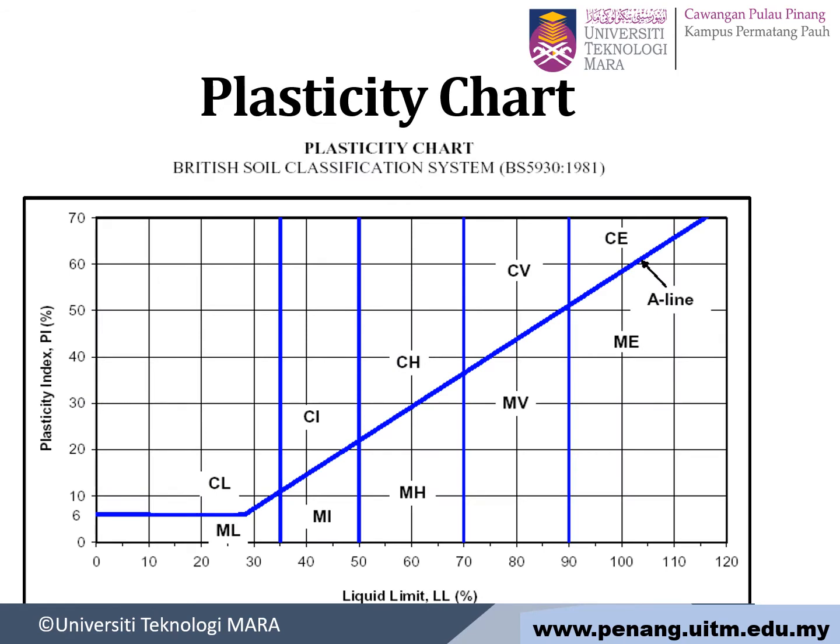Okay, this is a plasticity chart. If we see here, we see the plasticity index versus liquid limit. So from the plasticity index and liquid limit, you will classify the soil. Okay, you have to plot.